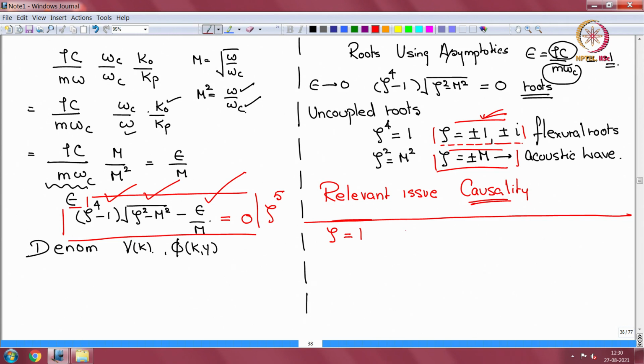Okay, so how do we do that? It's very simple. We choose a correction. We replace zeta with 1 plus a1 epsilon. I can do more, plus a2 epsilon squared, etc. But because I am showing by hand, I am going to take only one correction, so we will drop this term. So I am finding a correction to the plus 1 root from the plate flexure. Okay, so we substitute back into my equation.